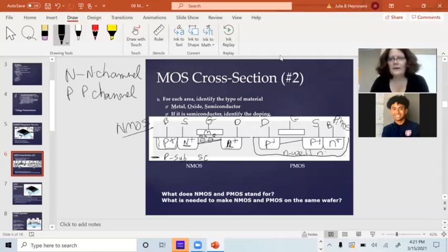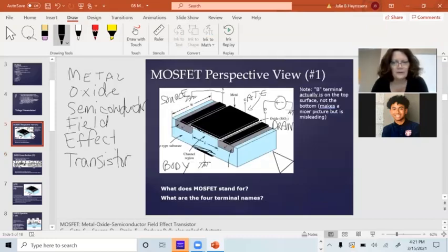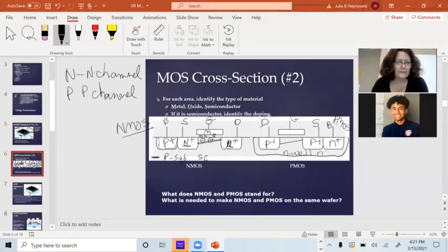Okay, we haven't talked about how it works yet. Is that not shown in the previous slide? So let's look at the previous slide. And no, yeah, you're right. The body connection is missing on this slide. And it's very commonly forgotten until your circuit doesn't work in the 380 lab. And then all of a sudden you realize, oh, I have to tie the body somewhere.